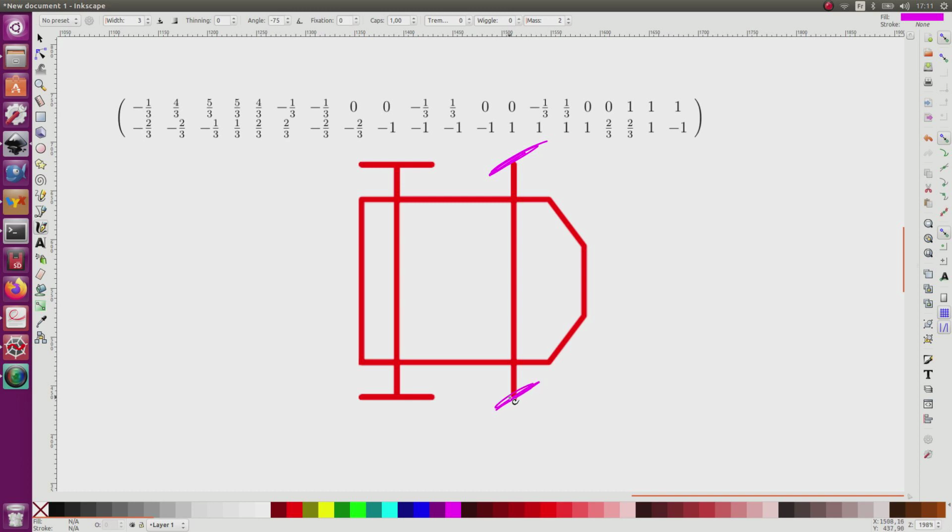So why do I have to separate? Because this one can move with respect to the red part, and this part is immobile, or rigid, in the sense that if I take two points, for instance this point and this point, then in the picture the distance between the two of them will be fixed. It is not the same if I take a front wheel like this, which will move. The distance between this point and another point, for instance this one, may change. This is why they have to be on a different sketch.